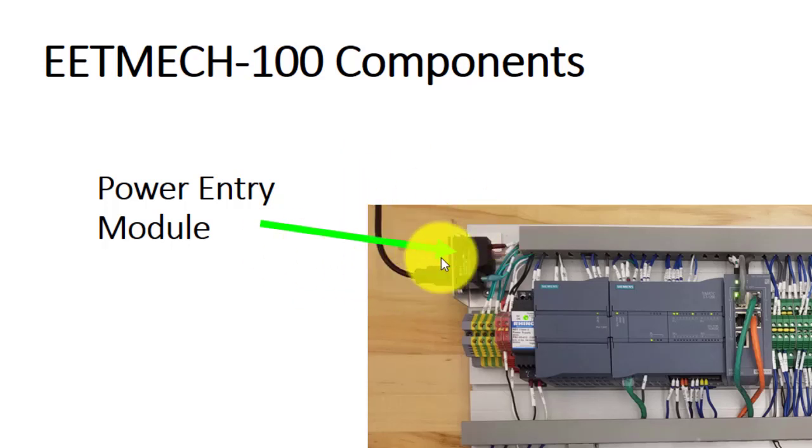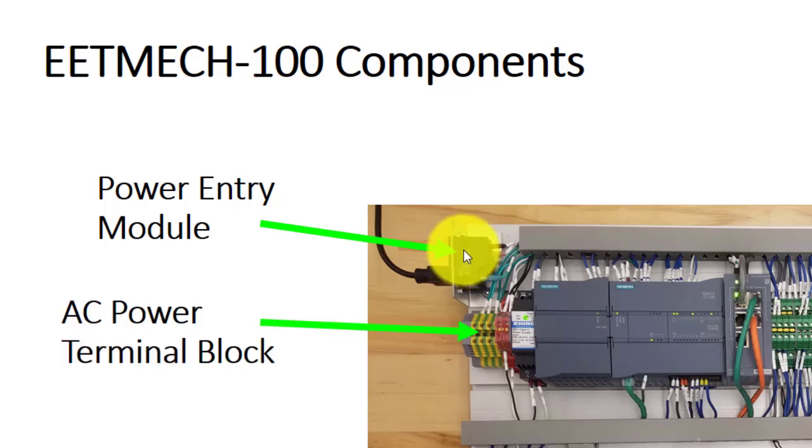There's also a switch on that power entry module and an LED that gives you an indication that the power is applied. The wiring from that comes into a terminal block carrying AC voltage. On the upper left, the red section is where the live voltage is, and those are insulated and covered over with a little warning safety cover. Then the green and yellow blocks are all earth ground for various earth ground connections, and the lower terminals on the red block are the neutral lines.